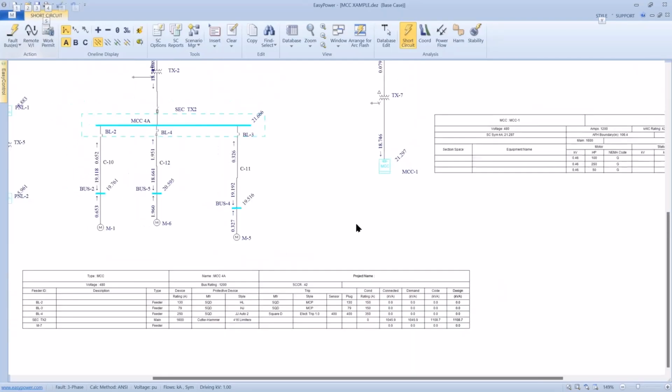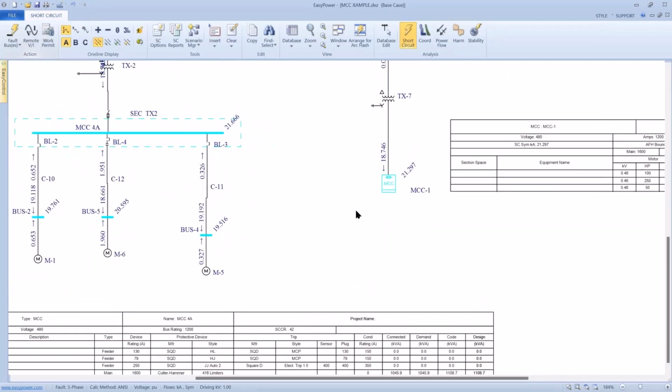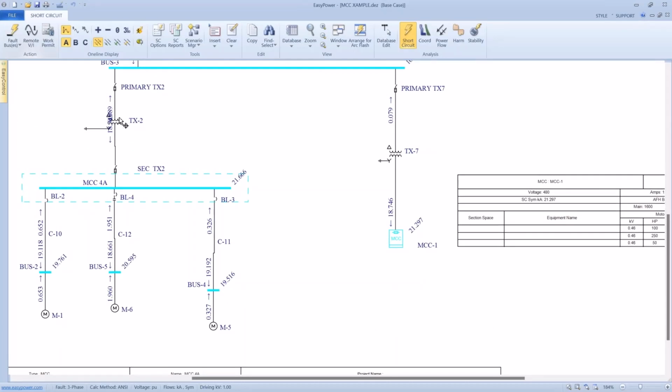Okay, so what we're trying to show, now this is where I wanted to be. So right now, based upon my initial trial, I'm showing a model of 18,745 short circuit current during the first half cycle coming from the transformer, and I show a 1 amp difference coming from the transformer in my MCC schedule.